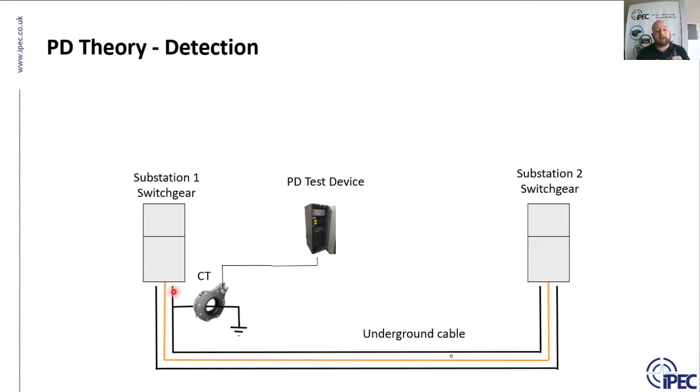If the earth is directly connected, what it means is that the HFCT must be installed on the core of the cable. Normally that also means that it must be installed inside the termination. So again, the only place where you can separate the two sometimes is on the core of the cable. Case by case, we look at that with customers, and we're always happy to help and consult if anybody is in doubt.